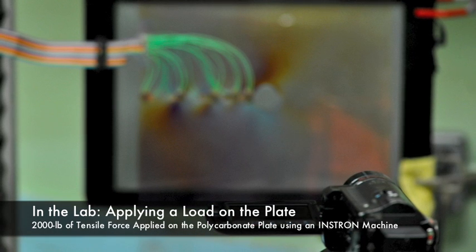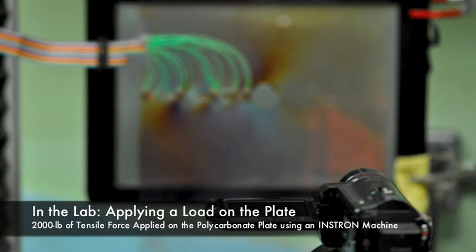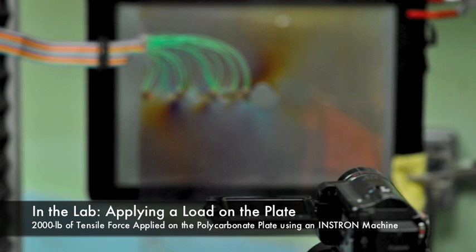The polycarbonate plate was loaded in the Instron machine using supports at the top and bottom of the plate. A screen that emits polarized light was placed behind the plate. This lit screen enabled us to see the stress concentration in the plate by passing polarized light through the plate. A Nikon DSLR and a Sony camcorder with polarized filters were then used to capture the photoelastic visualization in photos and video, respectively. 10 strain gauges were attached to the plate along the HH line to measure the strain.